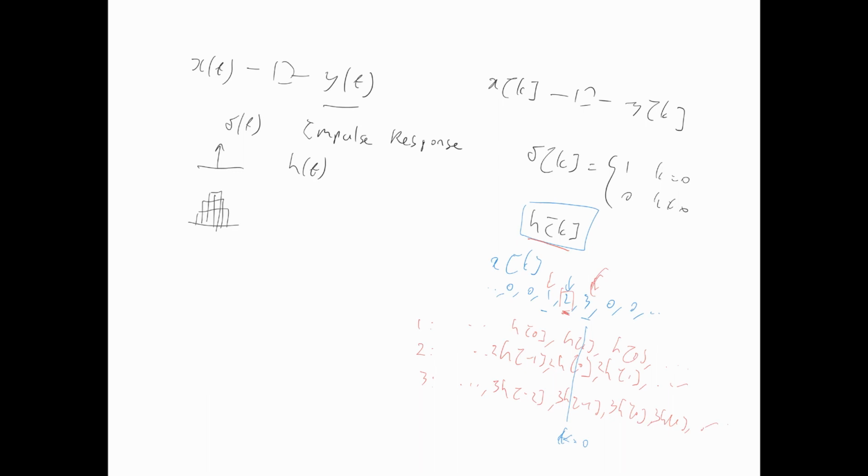And then my final output, my actual output, is given by just adding these up. That's the linearity of the channel. So in particular, at time 0, my output is going to be h1 plus 2h0 plus 3h -1. My output at time 1 is going to be h0 plus 2h1 plus 3h0, and so forth. The reason I wrote it that way was to try to show you intuitively what's happening. That's good for understanding, not so good for mathematical manipulation.